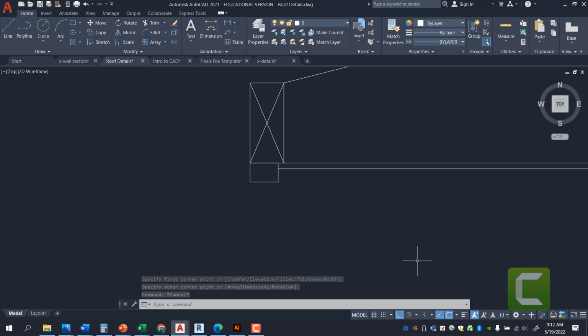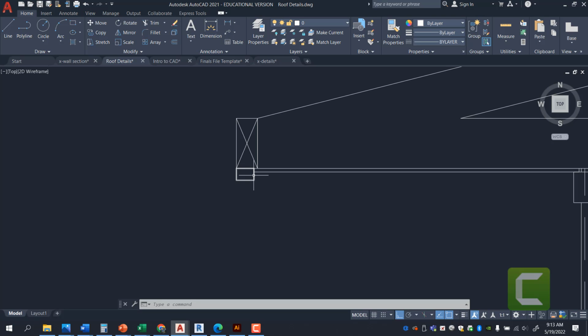They have trims. You can also buy weather-treated trims. This is really entirely up to your budget, how much you want to spend per linear foot based on client budget. But rest assured, what you want to do is with your trims, do not have them overlap onto your siding. Do not have them overlap. But you should be wrapping everything you can.